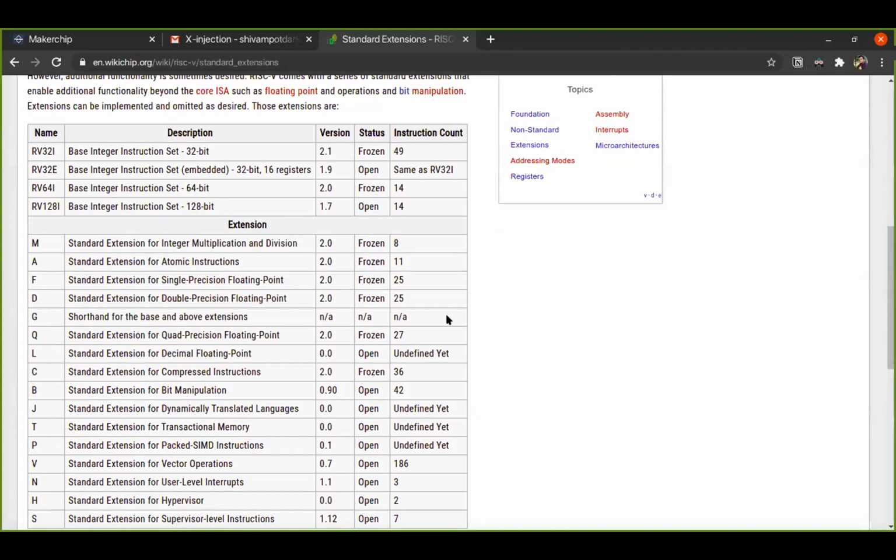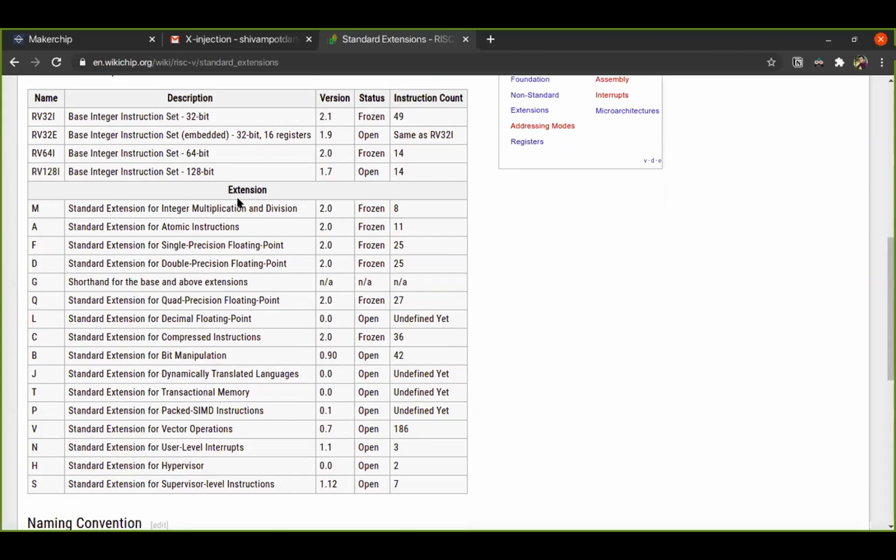And when you go down to something like a microprocessor, say Arduino, which is also a processor but at a very small scale, it's a microcontroller. It obviously would have limited functionality. It doesn't really need to support something like matrix multiplication, because that would make its cost higher and its structure more complex. So to handle everything from a microcontroller to a supercomputer, RISC-V has split the whole ISA definition into multiple extensions. RV32I is the basic one, which is integer operations: basic ALU operations, logical operations, and memory load/store. Then M has multiplication and division, as I said.